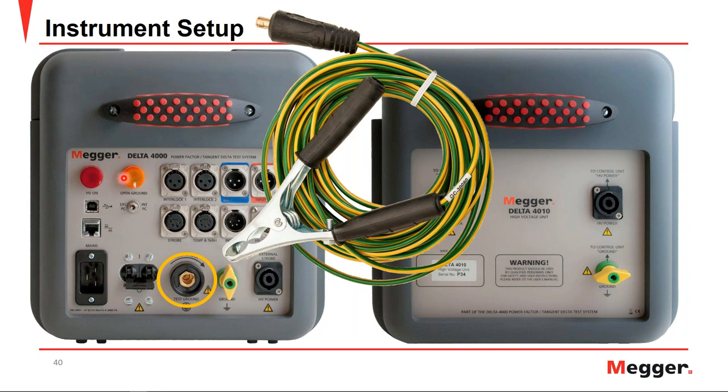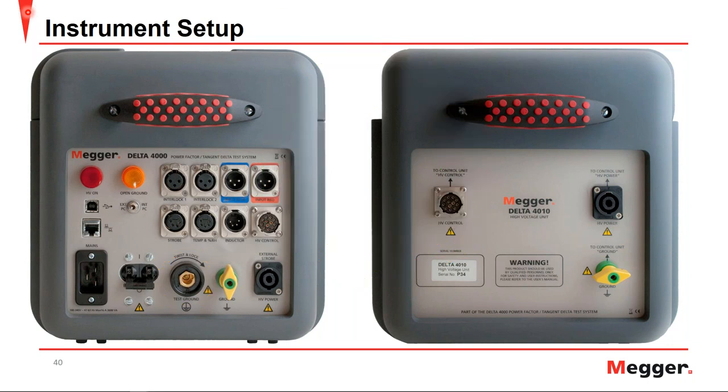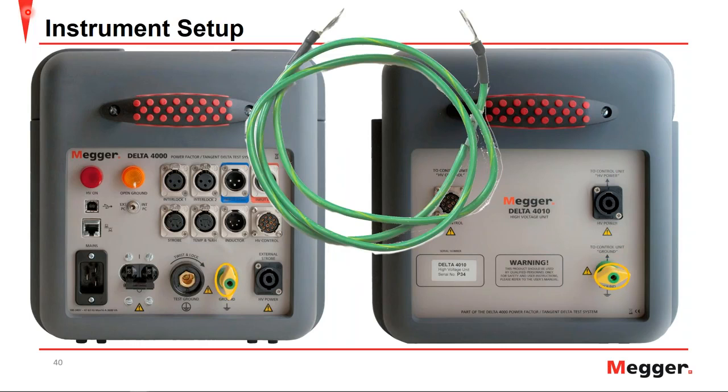And that is determined by this light here. This LED is the open ground LED, in which if there were an open ground, is illuminated, and once the grounds are all common, will turn off and allow you to perform a test, given that the interlocks are pressed, and we'll look into those a little later. Here we have the ground that interconnects the control unit and the high voltage unit.